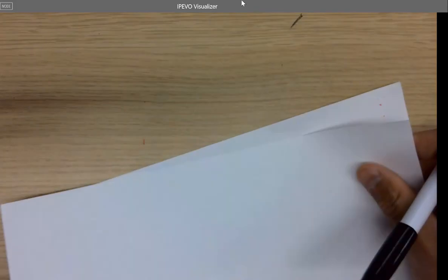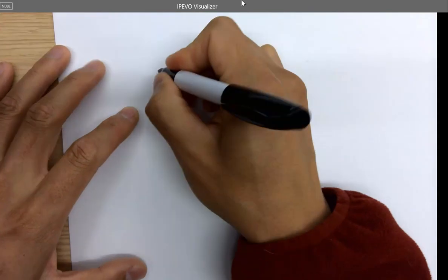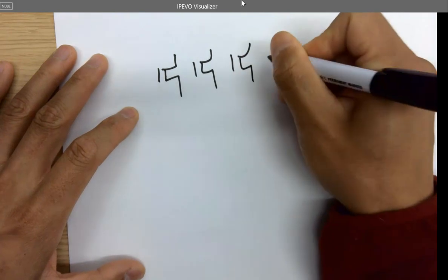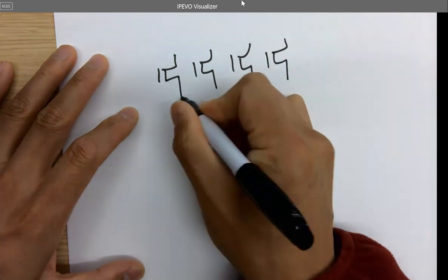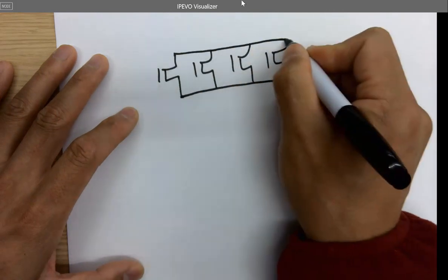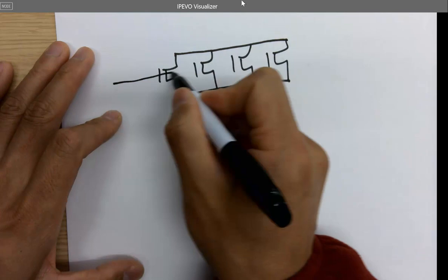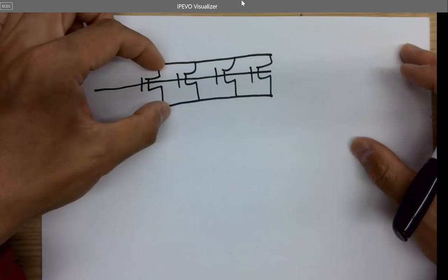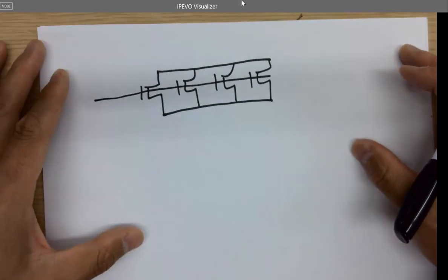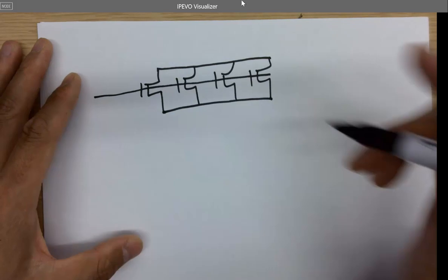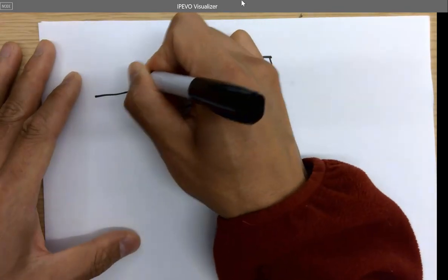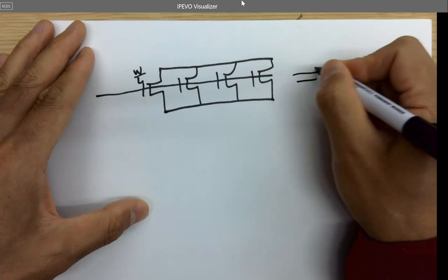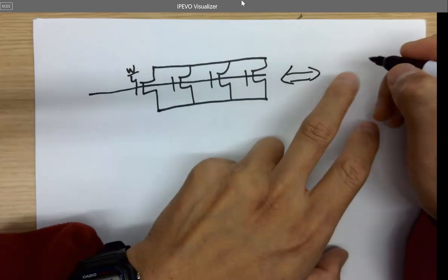So what if you have parallel transistors like this? The reason they are in parallel is because I shorted all the sources and the drains together. Again, they share the same gate. Are they in parallel? Yes. So channels are in parallel, definitely. So this, for example, each one is W over L, width over length. And the whole thing here is equivalent to one wider transistor.